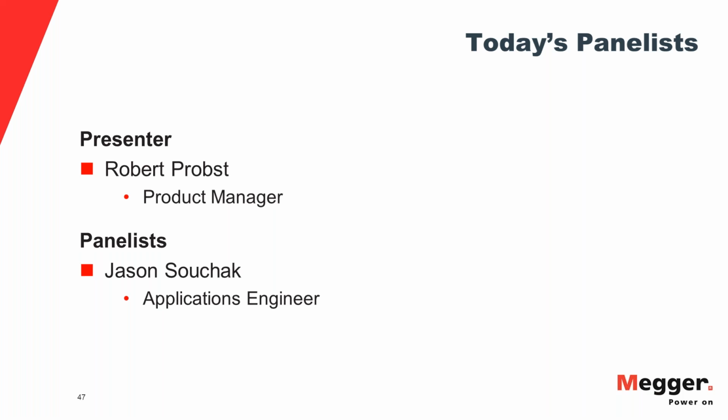Yeah, just to add this, the logic that IEEE applied here was the acceptance test, as Jason explained, is kind of you do the test and then you throw the switch, and nothing should happen if you pass the acceptance test. The installation test was introduced because it is the last chance for you to test the cable just as is, just before you start putting your hands on it, before you start mechanically and electrically changing it by putting on terminations and splices.